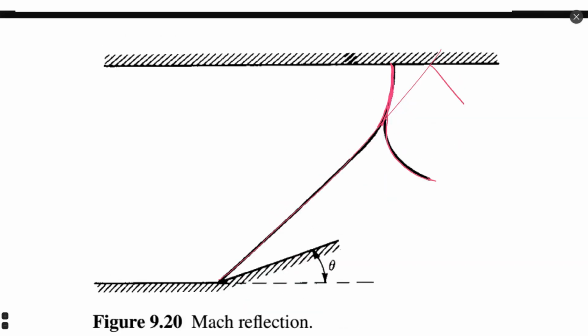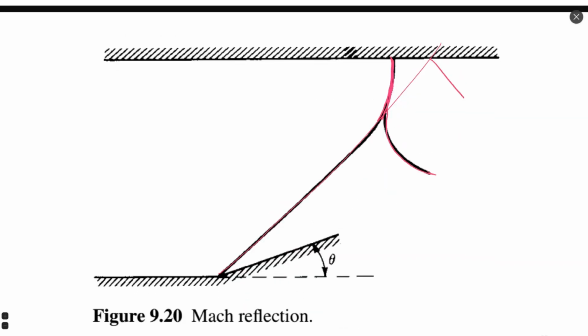We see the theta-beta-M diagram. If there is an intersection of the angle of the body and the Mach curve, it means that the oblique shock wave will reflect. If there is no intersection, it means that such a complex shape shock wave will appear that cannot be calculated analytically. We can stop this calculation.